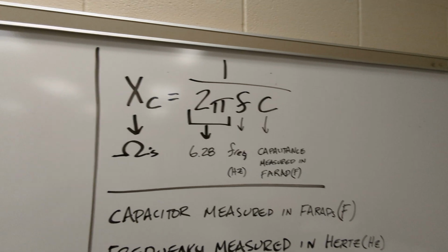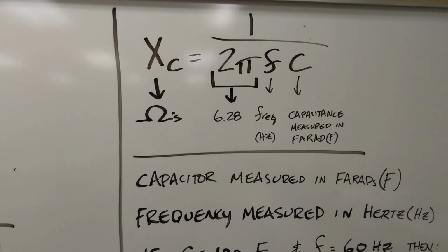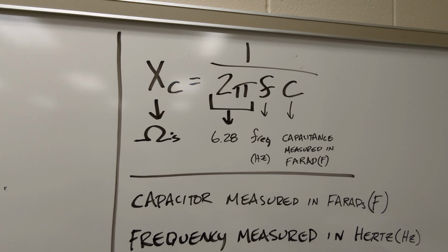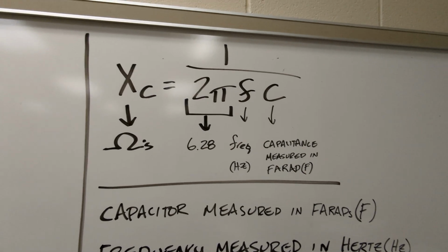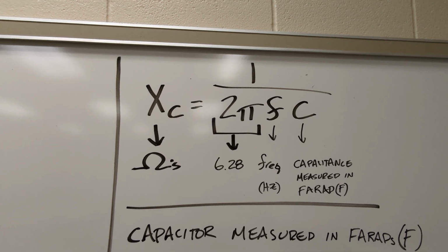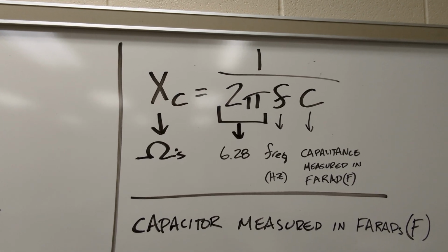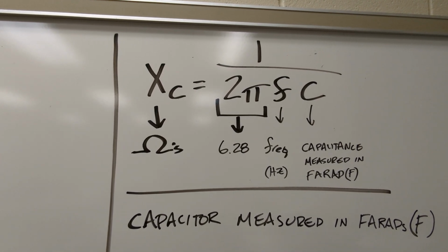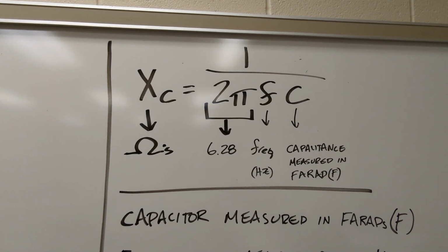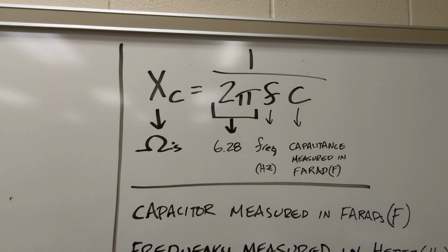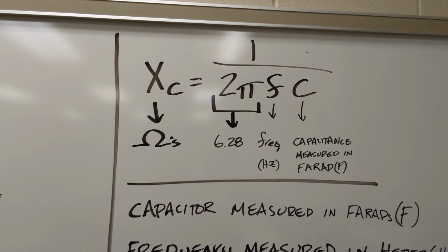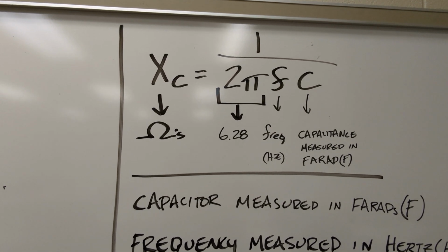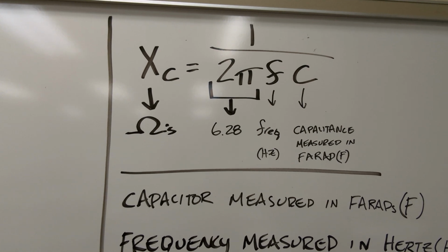And then finally, if we look over here at the capacitive reactance, that's 1 over 2 times pi times the frequency times the capacitance. And that's going to be an inverse. That's going to be over 1, or going to be under 1. Again, my 2 pi is just a mathematical constant, which is 6.28 in this case. Frequency is whatever value the power supply or the trainer is set to. And the capacitance is going to be a given value. That capacitance is measured in farads. A 1 farad capacitor is about the size of a Monster drink.